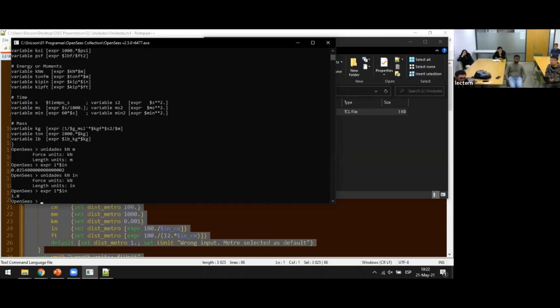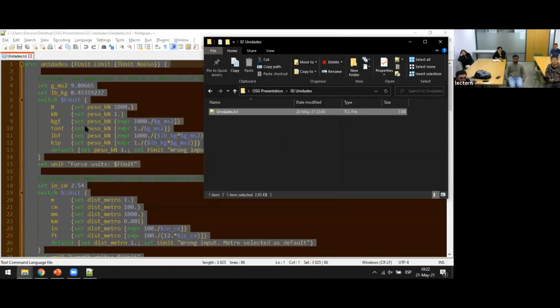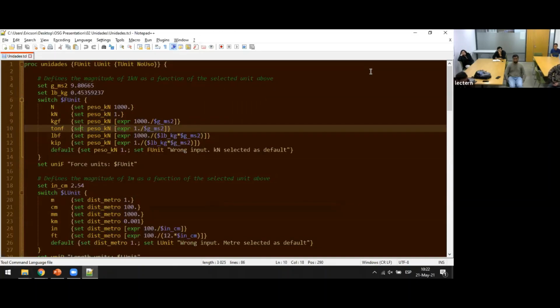And then if you put in a bond-slip model that you know needs ksi and inches, just go to the beginning of the script, change the base unit, and since everything is defined based on units, you don't need to do anything else. You need to have 2 files, but you don't need to modify the original lib units. So I think this is quite powerful, and it helped me a lot with all the definitions that I needed, and every time that I needed to change my models.